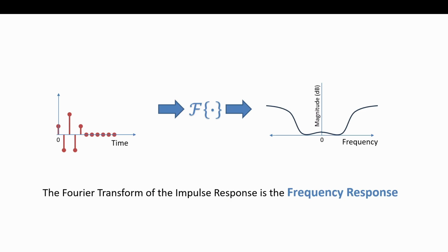One of the rookie filter design approaches is to use the FFT: I understand the FFT and the inverse FFT, so I should be able to just take the frequency response that I want, take the inverse FFT, and get the coefficients. Makes sense, right? And that is a design approach. That's one of the ones I'm going to show you. It's just one of the worst ones, and I'll show you why.